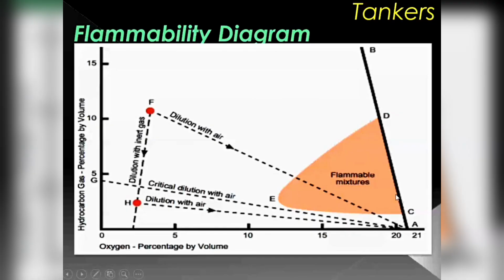All right. If it is 5%, the E will be somewhere here. So if I'm inerting, if I'm gas freeing, I have to inert the tank below 5% and then start putting the air inside, so that during the whole stage of my operation I stay in the safe atmosphere.